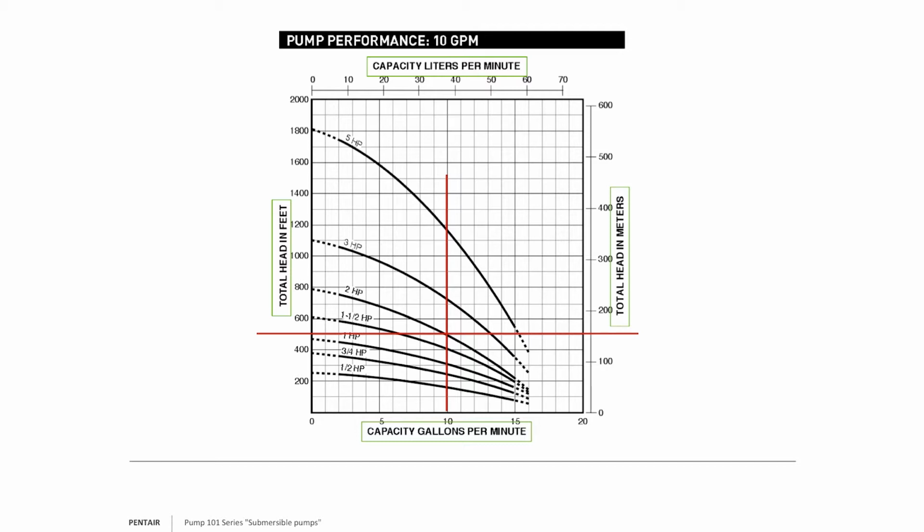Absolutely. Remember that example I just talked about with the chart, 350 feet depth to water and 60 psi? It was the same as doing basically 500 feet of head at 0 psi. In 500 feet of head, 143 feet can easily fit in there for the pressure calculation.